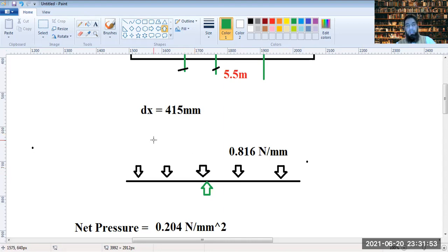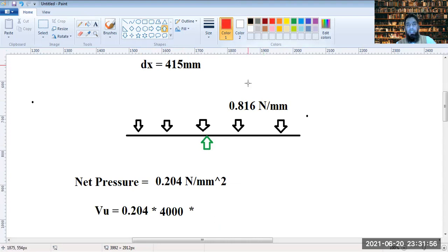This is becoming a cantilever now. This has a cantilever action on both sides of the support. So the shear force would be zero at the free ends of this cantilever, and the maximum would be at the support. But now the support itself is a big entity.